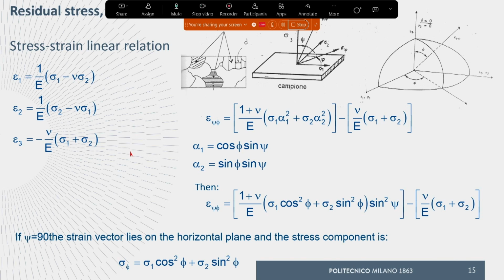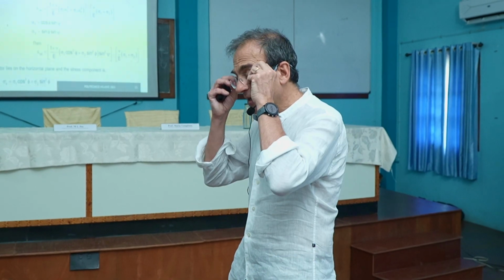Sir, in that case, here, sir, here. Sorry? Here. Yeah, for sure. So that means the residual stress measurement using XRD is a comparative method. We are using the measurement, and we consider as a base condition the undeformed condition, where the diffraction peak corresponds to the peak that we have without any stress applied.